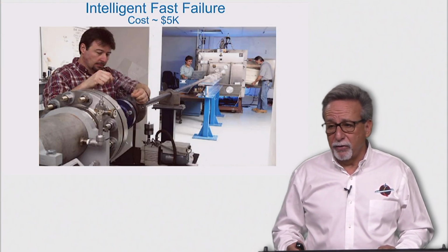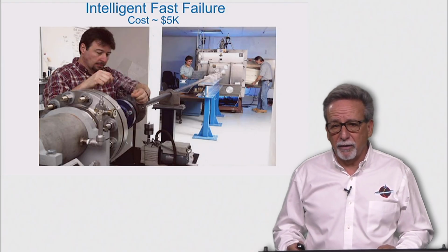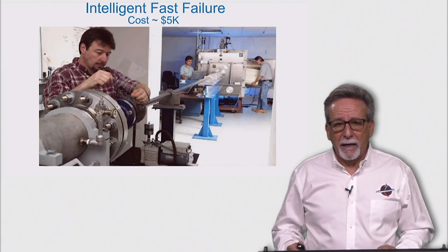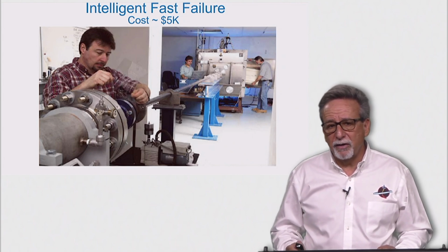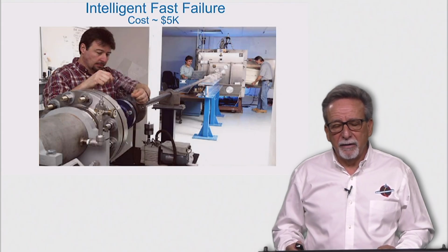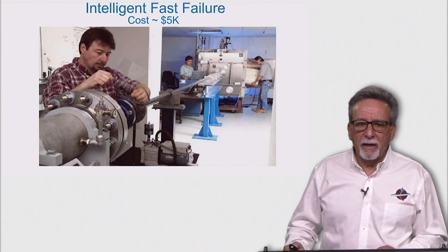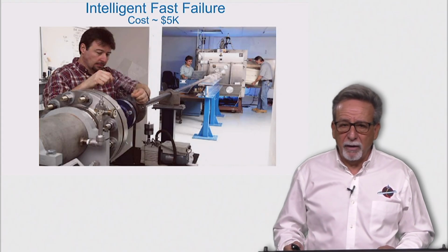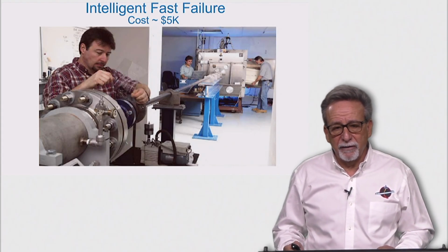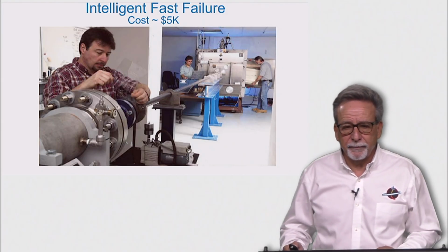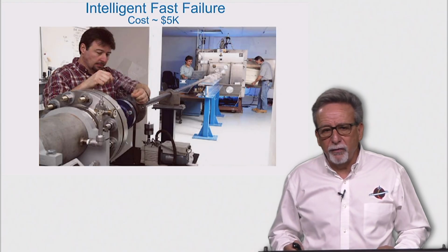Immediately, the folks at Glenn Research Center, under the supervision of now Center Director Dr. Woodrow Whitlow and led by Matthew Melis, configured their ballistic gun at Glenn Research Center to start testing foam and RCC material. The team at Glenn was linked to the landing impact dynamics specialists at NASA Langley, and together with Boeing Philadelphia, they created a research program to rapidly gain sufficient knowledge to understand the physics of the ET foam debris impact to an RCC wing leading edge. They were able to do this in less than 3 months and for very little money.